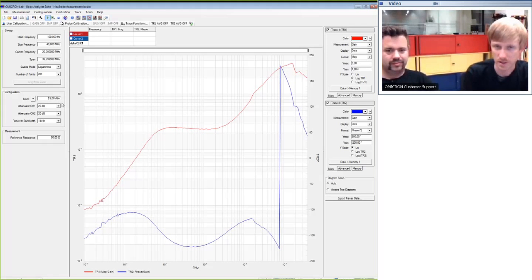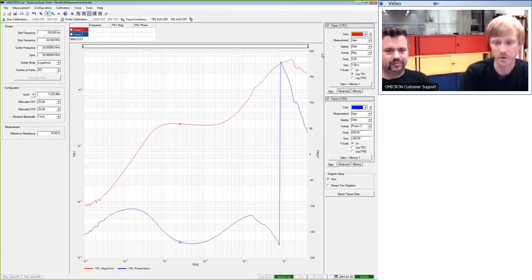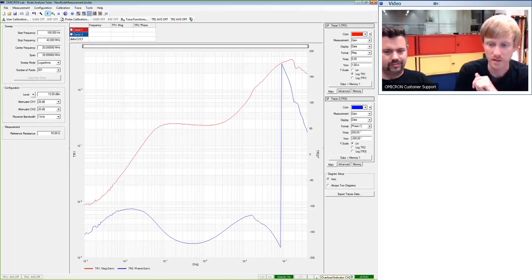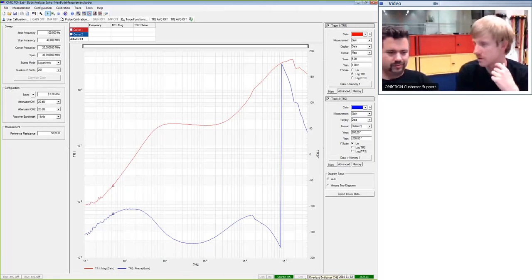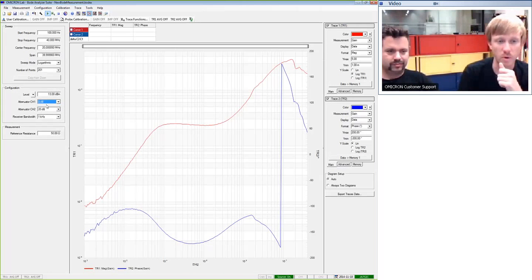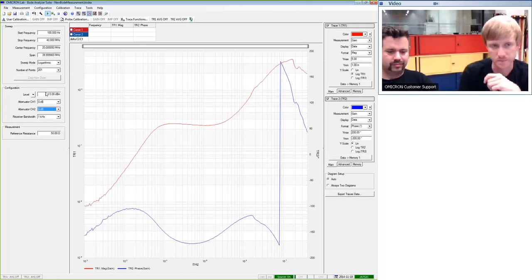What we can do in addition is we can reduce the attenuators on channel 1 and channel 2. The reason why we can reduce it is that we can see here on the overload indicator on the right hand bottom side that we nearly have no signal on the ADC. So we can reduce the attenuators to have more signal on the ADCs to get less noise on the result.